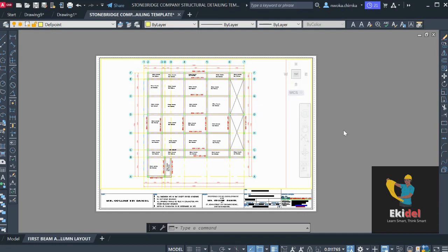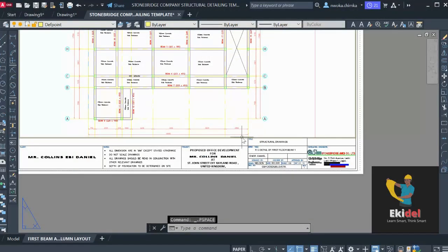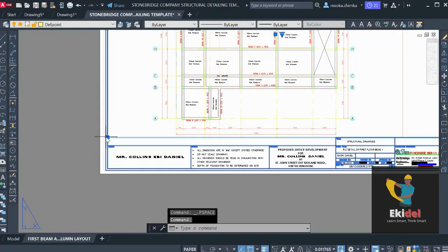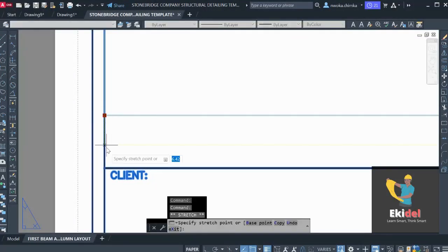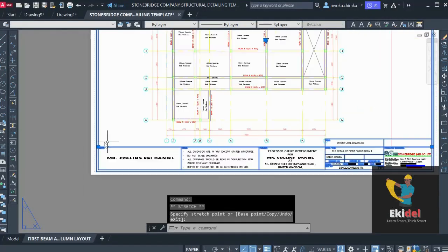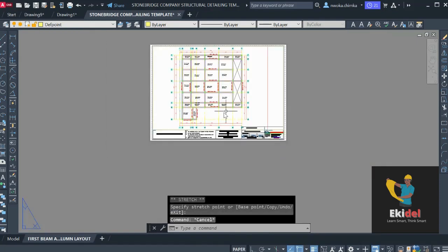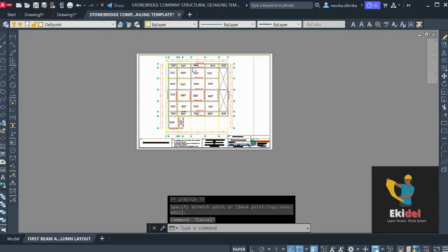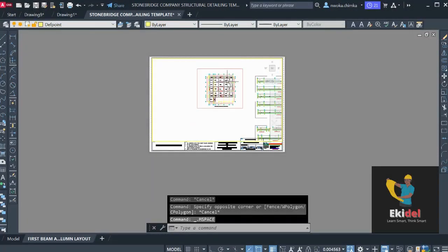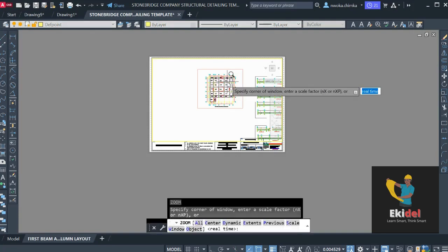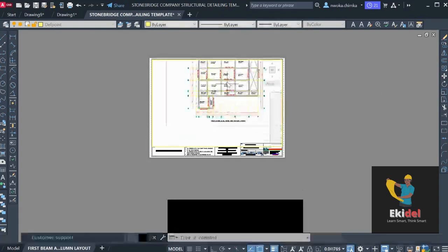Yes. So if we go right now and extend this viewport space down to this place, if we click this from this point and extend it down here, you can see everything. Okay, you can see it here right now. So if you double click again on this point, you can see what is happening right here. If you type Z, enter, 1 all over 85, which is our scale, then type SP, then press enter and see what is happening.